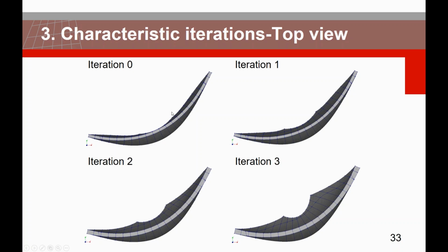And at the same time, we see in the downstream phase that the side parabolas are added, because here you see that we cannot even see the downstream phase, while when we go to iteration 1, we see that the downstream phase is more apparent. And as we go into iterations 2 and 3, in the end we see that in iteration 3, these parabolas around the foundation of the dam are much steeper.